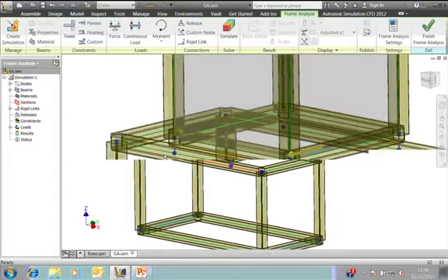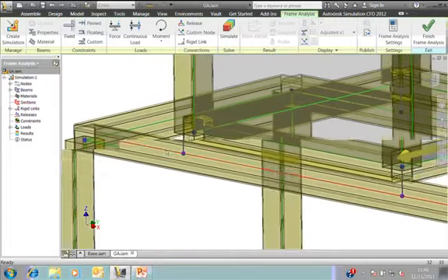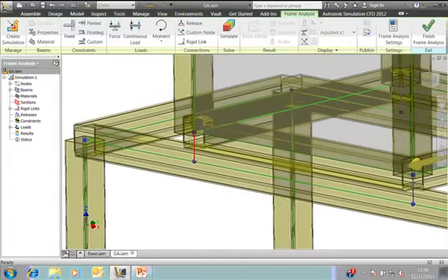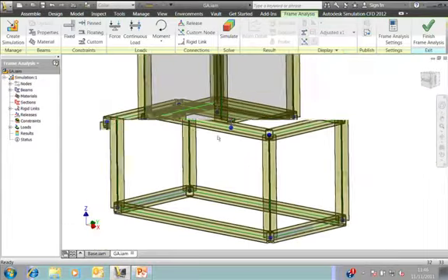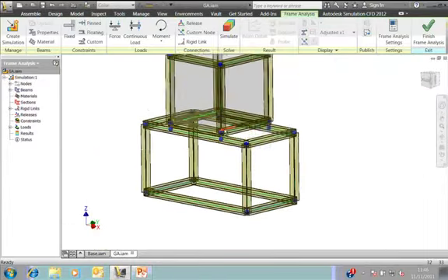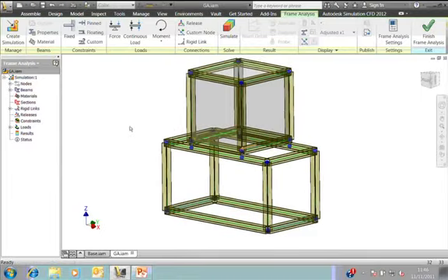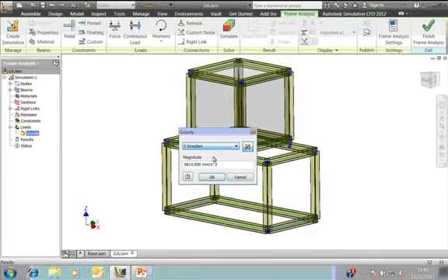Where the two assemblies connect, we've actually got a rigid link here which connects the two nodes together, so the forces of the one node is transferred to the force of the node below on the other side of the rigid link. The yellow arrow here, which you can just see, is gravity, which obviously in this case is in the wrong direction. So the first thing we would do is we'd actually change gravity, put that in the right direction.